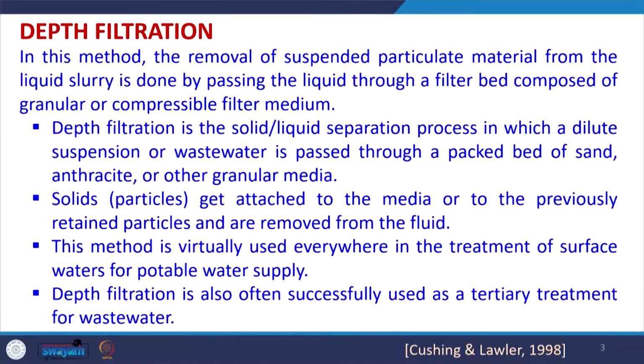In this method we remove the suspended particulate matter from the liquid slurry by passing the liquid through a filter bed composed of granular or compressible filter medium. It may be incompressible or a little bit compressible, and we pass the slurry through it. All the suspended particulate matter gets filtered out, or blocked, because of the smaller pore size as compared to the size of the suspended particulate matter.